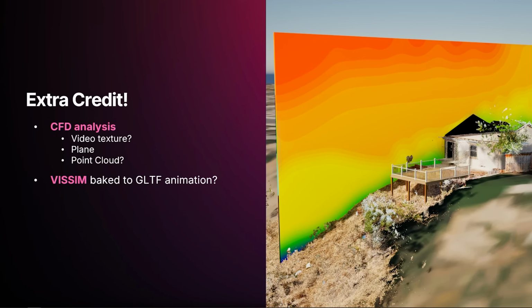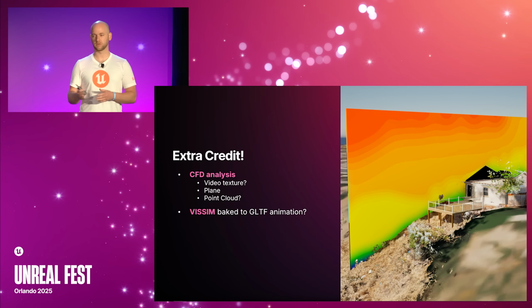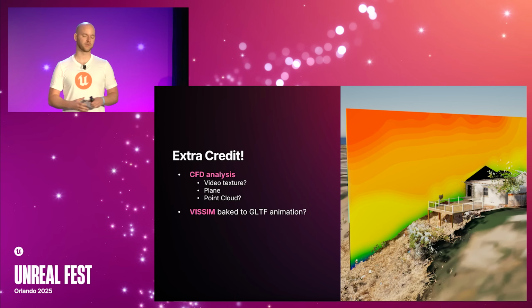I have a slide for extra credit because I didn't have the time or skill to do these things, but one topic is CFD analysis. You're not going to do your CFD analysis inside of Twinmotion, but I think there is an opportunity to at least present your findings here. So a lot of those tools will spit out like a plane with your CFD data, or like a video texture that you could bring into Unreal Engine and use it as part of your presentation. And similarly, you probably have some volumetric data that could be baked out into a point cloud, and you can bring that into Twinmotion to interact with it.